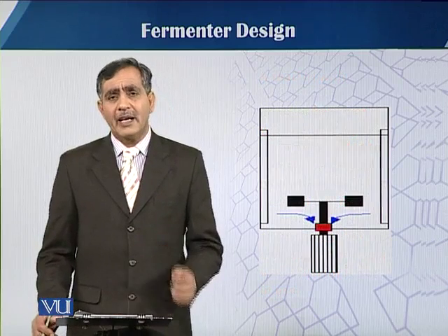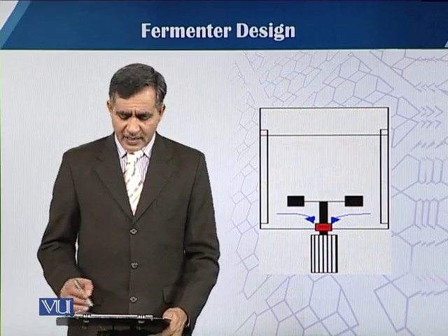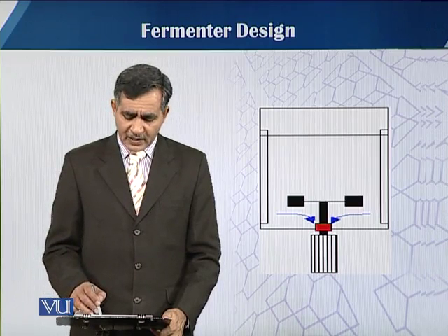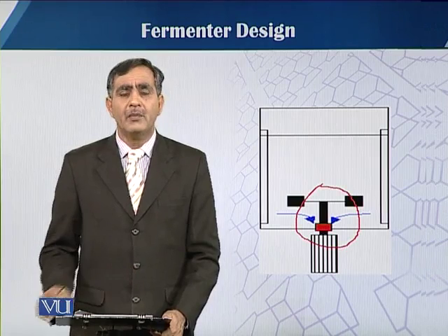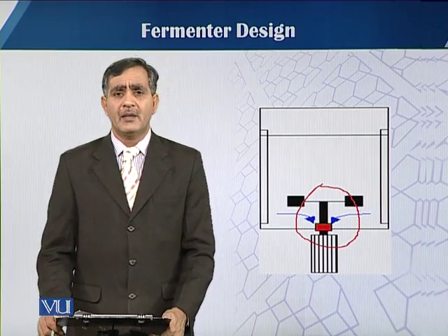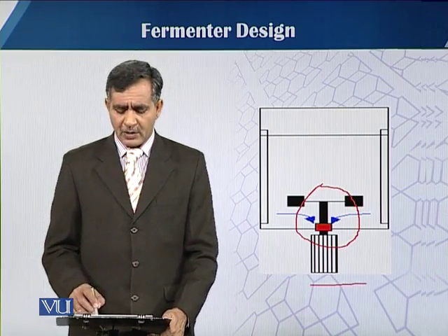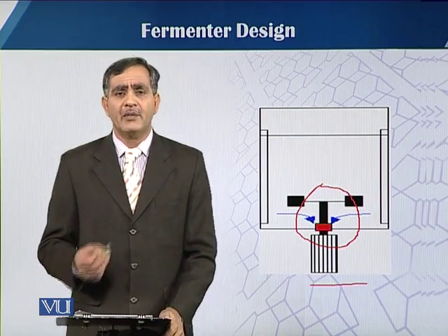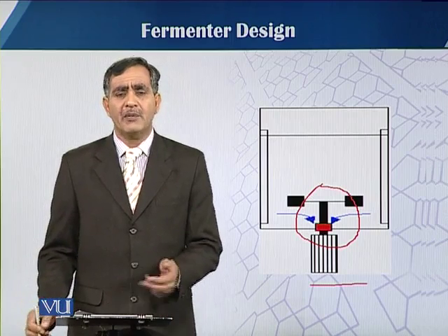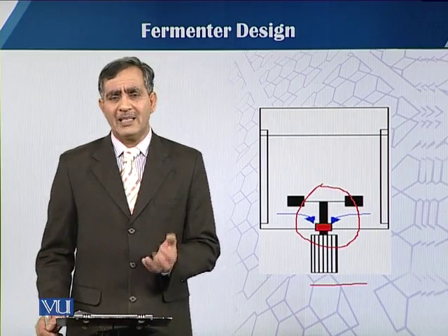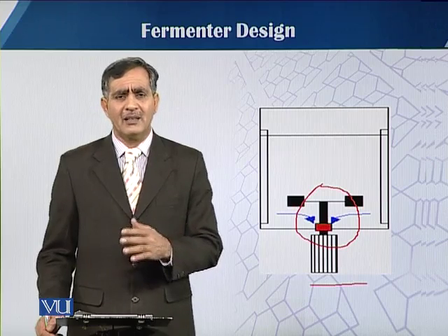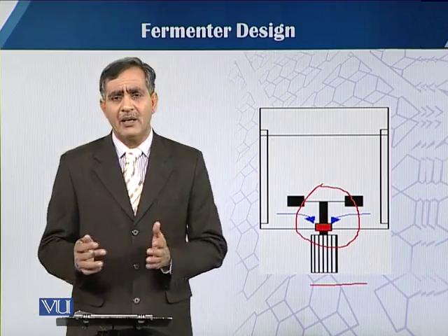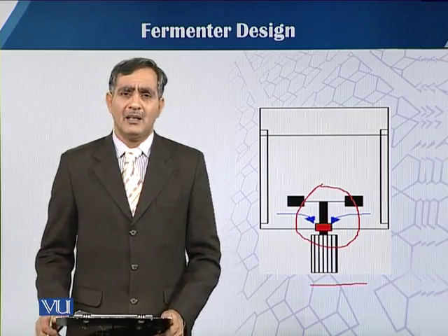In this diagram, we can easily observe how the shaft enters from the bottom of the fermenter, because the motor is placed on the bottom, so the shaft has to enter from the bottom. In this case, we have the problem that when there is precipitation or crystals and some other salt present in the medium, that can affect and disturb the seal quality.